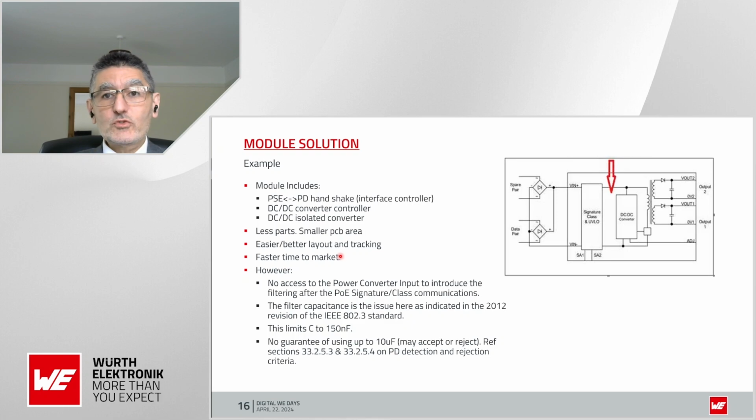And finally, and most importantly, is the introduction of filtering, which is not going to be feasible when you have got a module like this. Where you see the arrow introduced here is where you can introduce input differential and common mode filtering for this stage. You can't introduce filtering on the front end here.